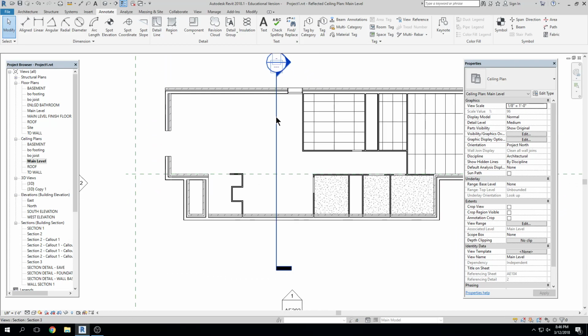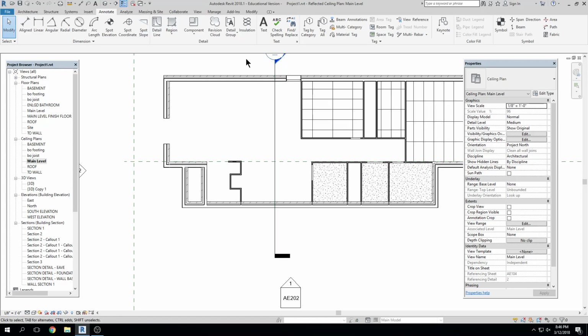Okay. So there are going to be times in your ceilings where you have areas that need to be lower than others. Well, not in here, although this ceiling is lower than the deck. But there are going to be times when it has to drop to accommodate structure or ventilation or its design intent. You want to have a lower space, essentially. And so we'll have to create what's called a soffit. The soffit is going to consist of the ceiling being dropped, but also we have to fill in the area where the ceiling drops. So let me show you what that looks like.